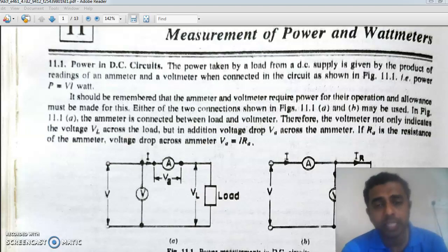But MI instruments can accept bidirectional flow of current because torque is more or less directly proportional to the square of the current value. Due to that, the torque becomes unidirectional irrespective of the direction of current flow. So MI instruments, although they are mainly used for measurement of AC voltages and currents, can be used for measurement of DC values also.